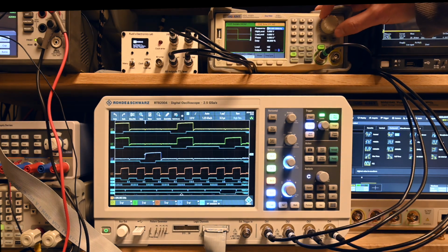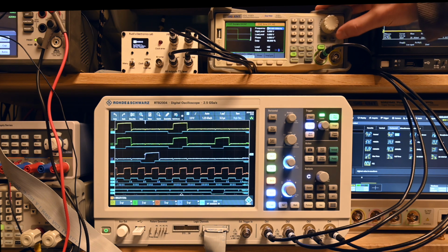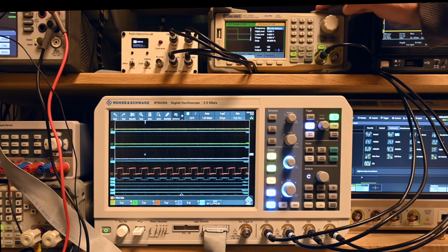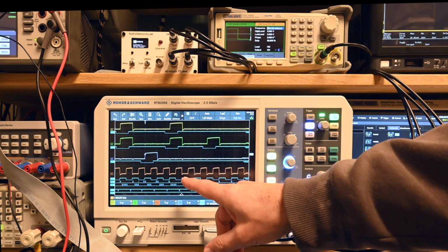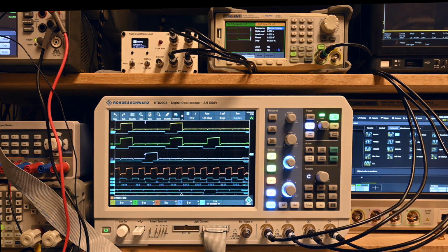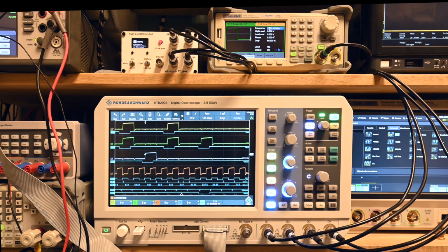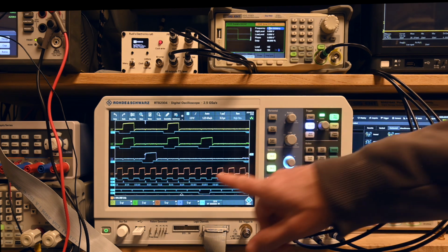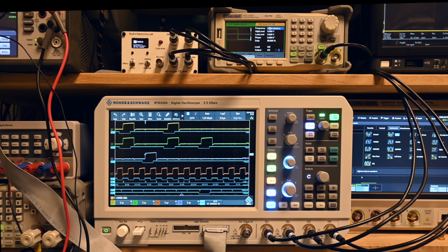So 700 kilohertz is still kind of going fine. 800 kilohertz is still going fine. Sometimes there's just one single wait state. 900 is still kind of going okay, but we're at the edge here. So sometimes there's just one single wait state to wait until it has to deliver. And if we go further up, then we see the error light on the device going on, and that is basically telling us that it can no longer keep up. And we can also see that on the scope here, because sometimes there is simply no wait state anymore.